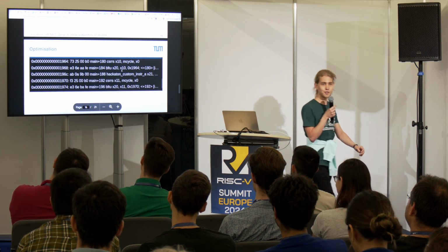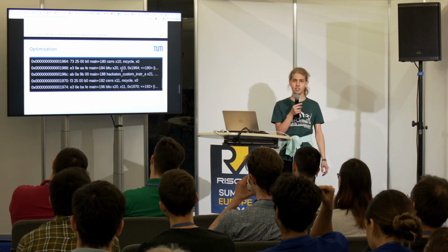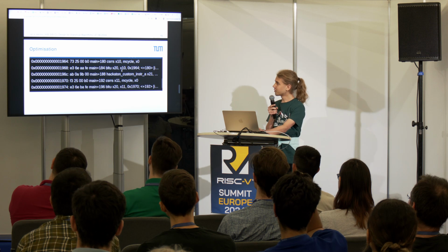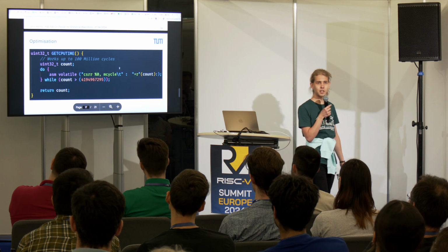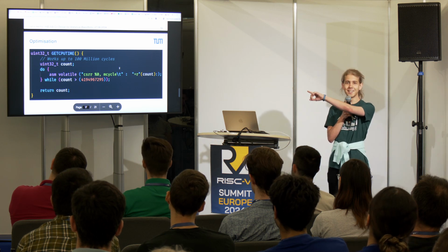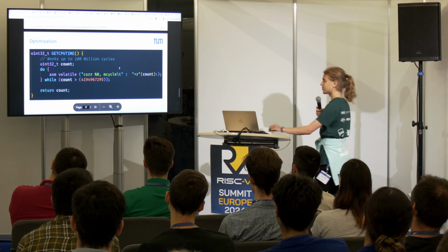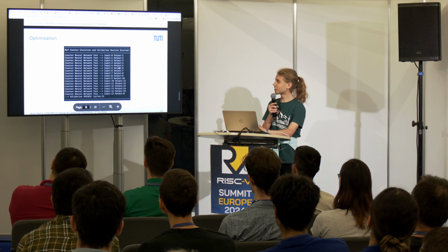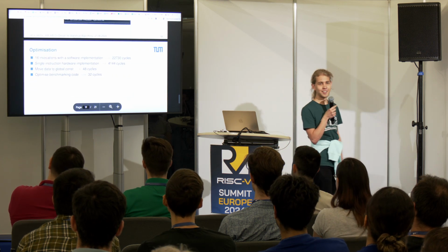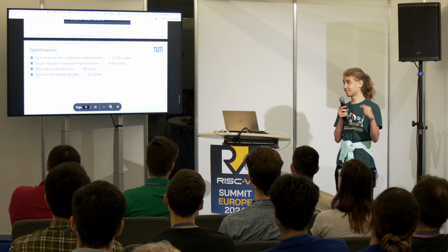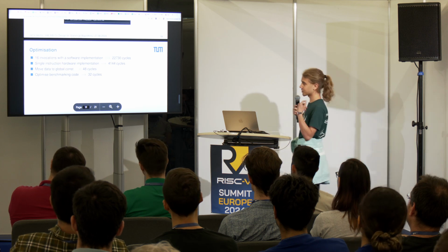This is the generated assembly code. The top two and bottom two instructions are part of the benchmarking code. There's this branch in here for some reason. This is the corresponding C code. I don't know what this while loop does. If you could tell me later, that would be great. But the cycle count never goes above this number, so I decided to just remove it. And with that, we've shaved off another 16 cycles. So I'm pretty sure this is the lowest you can go, because the instruction to store the current number of cycles also takes one cycle, and there's 16 iterations.